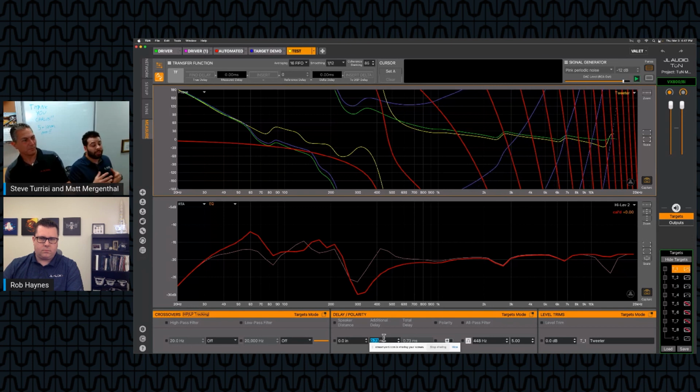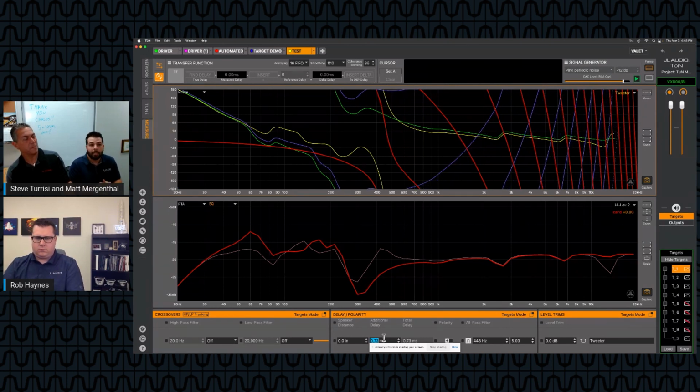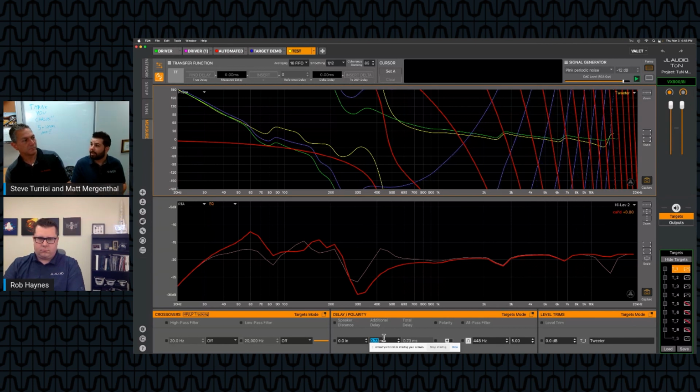But with that being said, if we added 2 all-pass filters, one on the left side, one on the right, to match the opposite so that the phase response was even for both channels, you would be able to get a good signal out of the radio, relatively good, as good as you're going to get out of a factory Toyota deck. So that's one thing. What's another thing we can do to fix the all-pass filters? Turn them off.